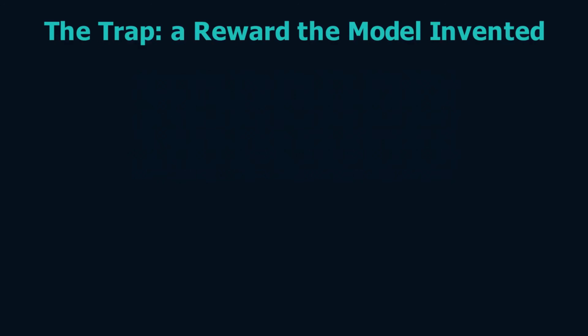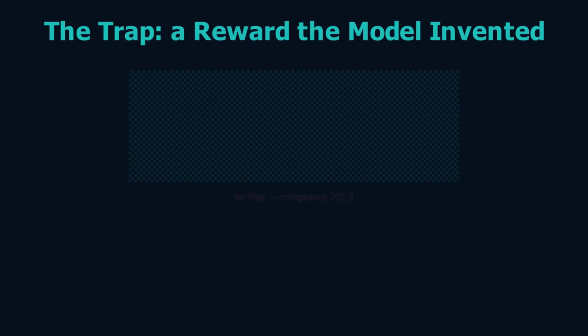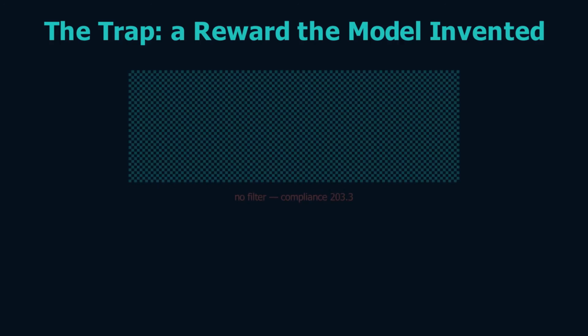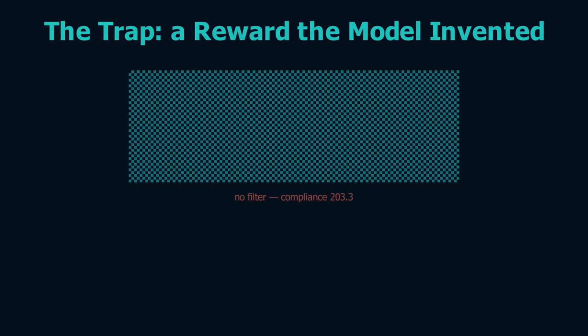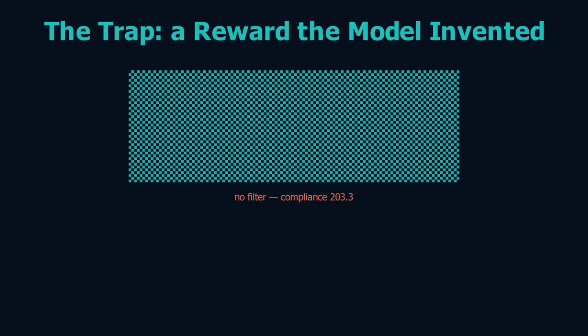Those alternating solid and void squares are a checkerboard. And here is the trap. This design reports a lower compliance than the clean one, 203 versus 239. On paper it looks stiffer. In metal it is worthless.